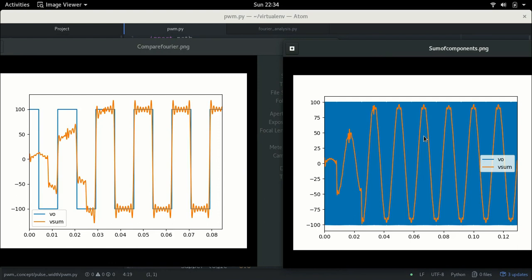The lower frequency harmonics are almost negligible, and the resultant waveform is much closer to a sinusoidal waveform than it is in the case of a rectangular wave modulation. This may seem like an AC voltage, and this may not seem like an AC voltage, the blue line in this case, but the blue line is surprisingly closer to a sinusoidal AC voltage than this rectangular waveform. And that's what this simulation example shows you.